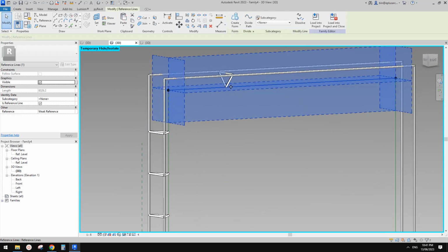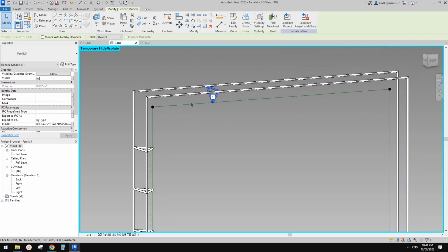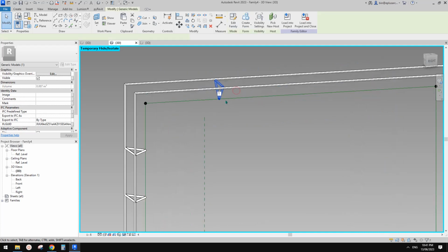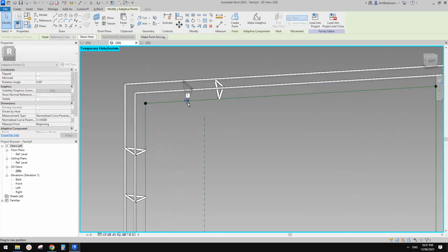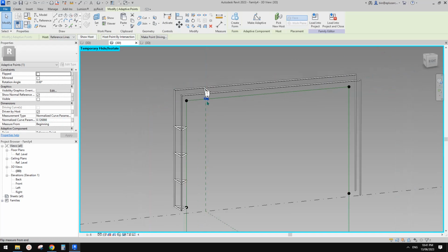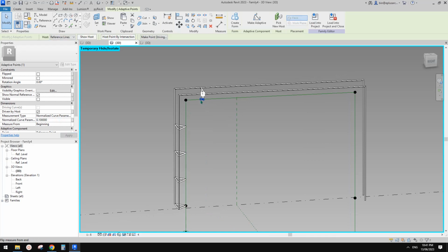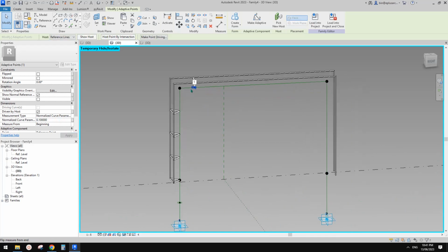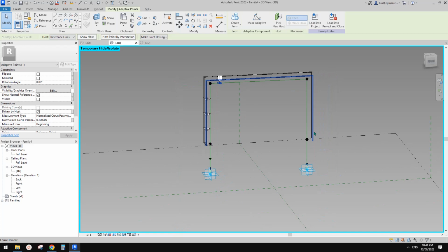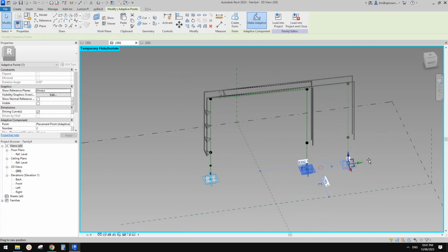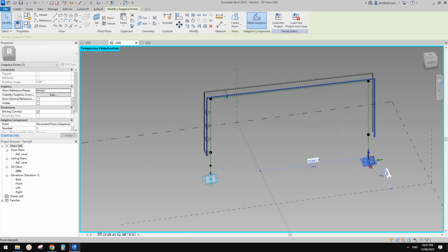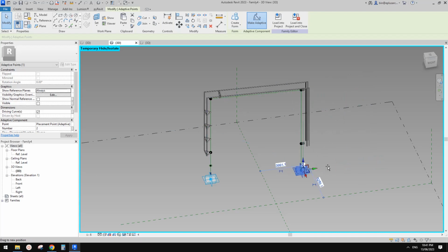So great. You just manually place them onto this, and because by default it's using a normalized curve parameter, it's using like a percentage of the overall width. If you place it at 0.1, it will always be at this point, like 10% of the overall width. If we move the point to 2, you will see this will adjust accordingly, right? So good.